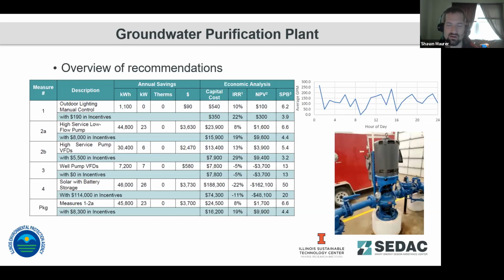What you can't see here is that, for the most part, these average flows for the month, you had a peak early in the morning, a peak at about 3 to 4 o'clock in the afternoon, and then a smaller peak later in the evening, about 7 to 8 o'clock. The other spikes are intermittent, but there is this consistent, every night at midnight, spike in energy consumption because the pumps would kick on at almost that exact time every night.